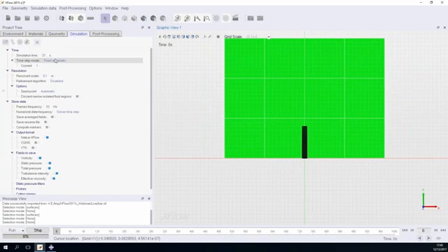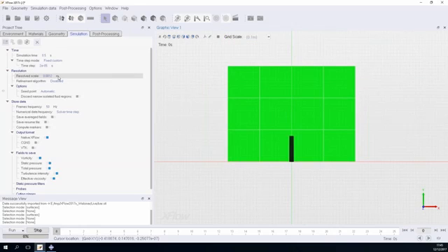I have my boundary conditions, and now I'm setting my simulation time that, as we said, is going to be the same in Abaqus and XFlow, 0.5 seconds. I'm going to specify a custom time step in XFlow, and it's going to be a uniform resolution in this case, so my lattice is going to be all uniform and 1.2 millimeter. Perfect.